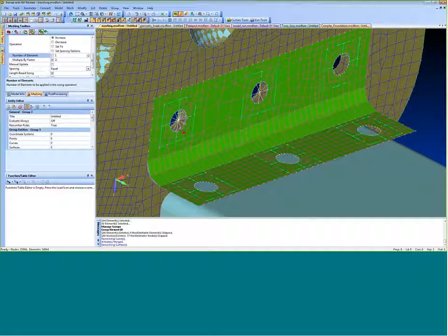So if you look again here, you originally have 4 nodes along this curve and 4 RVE legs. You click it again, now it is doubled. And the whole mesh updates, and now the RVE goes along with it. Now there is a limitation to this, and it is an intentional limitation. Let's say I want to do it for this guy. Notice that this RVE does not have a leg for every single node along the curves. Maybe that's what the user wants, maybe the user forgot. But for this example, I'm going to click on this edge. The bracket updates, but the RVE doesn't.